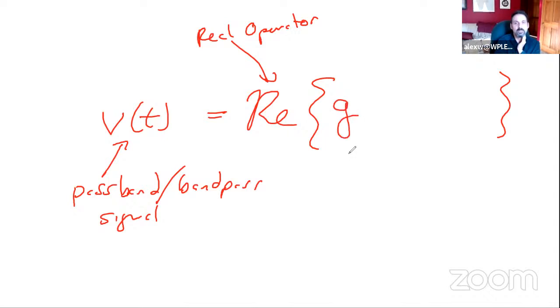You see it in the slide as g(t). I'm going to put a little space here, and then you see e to the j. Instead of omega c, I'm going to put 2 pi fc t. This is what we're going to call our carrier frequency. Bandpass or passband communications implies that the ultimate signal has been modulated up to and is centered at minus fc and plus fc.